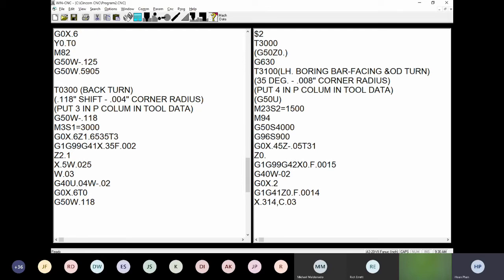And then the next thing we're going to do is the Z move. The part Z move right here, the distance is going to be .393710 minus the gap right here, .059. So the finish point is going to be .3347.